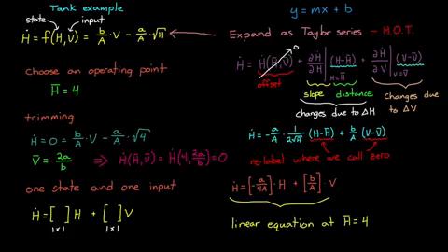What we did here was Jacobian linearization. We built a linear model by looking at the first order derivatives of the system. And this type of linearization requires the function be differentiable at the operating point. But there are other linearization methods as well, and in the next video we'll explore some of those other methods, what tools exist for them, and how to understand what they're doing under the hood.